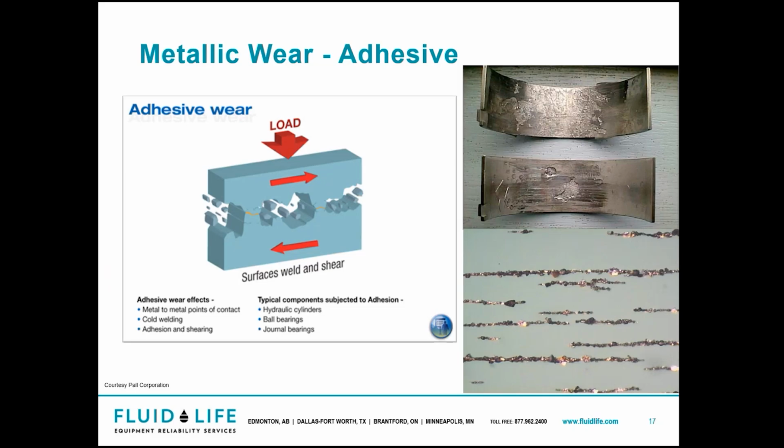Now we see the wear metal here, the strings of metal. These are probably 10, 20 micron in length and maybe a couple micron in width. So these are actually not that big of an issue.